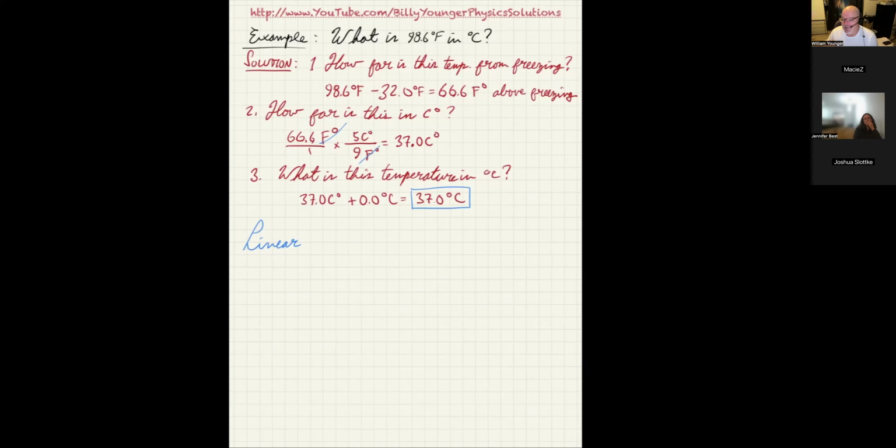So when you have a linear expansion, what we're talking about is one long dimension is expanding. The other ones aren't necessarily that big of a deal. So later that will be compared to, instead of a linear expansion, an areal expansion where you're talking about a whole area expanding, or a volumetric expansion, in which case you're talking about a whole volume expanding. So linear expansion,